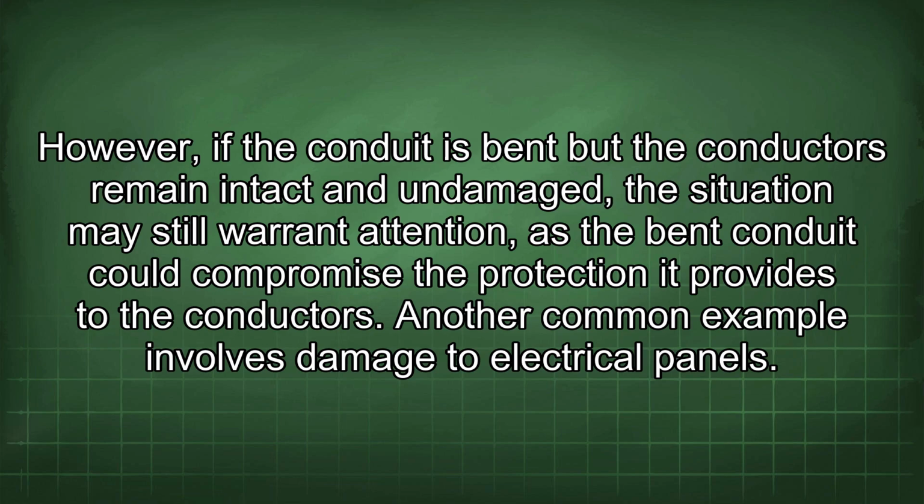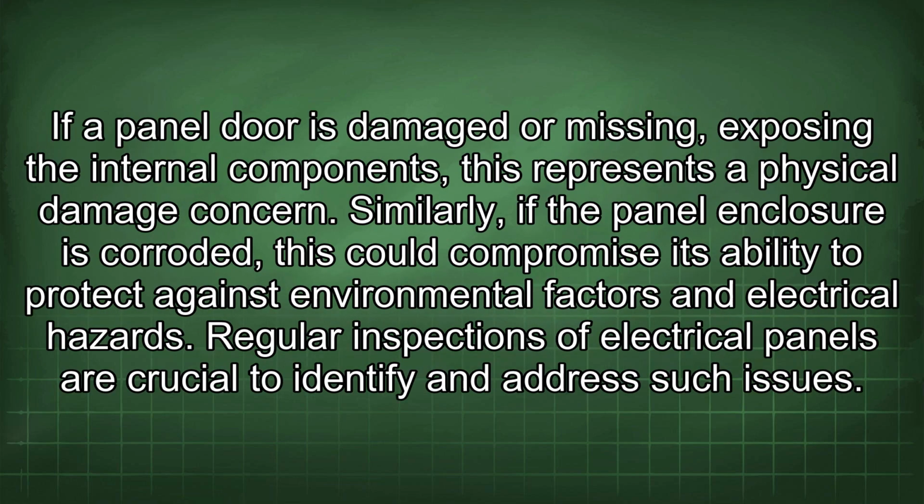Another common example involves damage to electrical panels. If a panel door is damaged or missing, exposing the internal components, this represents a physical damage concern. Similarly, if the panel enclosure is corroded, this could compromise its ability to protect against environmental factors and electrical hazards. Regular inspections of electrical panels are crucial to identify and address such issues.